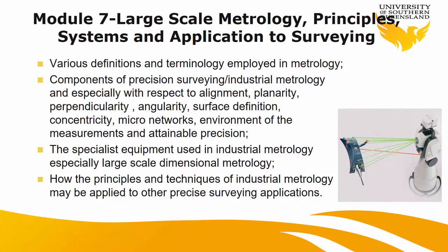Module 7, we had about metrology, yeah, large-scale metrology, which is mostly used in industry. I know there are limited surveying firms using metrology, but this is asked by the accreditation body that we need to cover that, because even if one or two of you end up working there, we have to make sure you've got enough knowledge, yeah? So we talk about laser tracker, laser radar, different systems, yeah? Precise leveling, how we actually measure the flatness, yeah? Measuring the verticality, and what type of target we use.